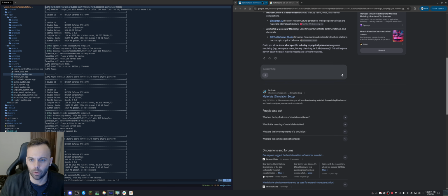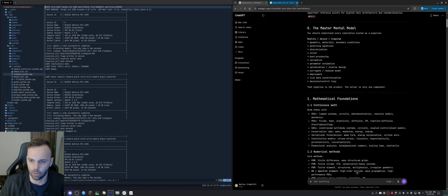Okay. Boundary conditions. This is like your inlets and outlets. Kind of where the simulation begins and ends. The mesh itself, in a lot of these I've used, voxelize the mesh into 3D, and each voxel can have a flag representing if there's a solid there or a boundary, but it gets really complex, especially different meshing techniques, which I definitely don't have a firm grasp on now, but you rarely ever uniformly mesh things.